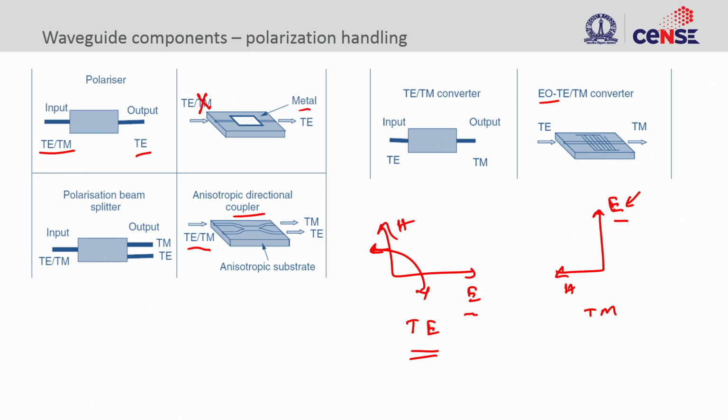So, that is another way of handling polarization conversion. You can also do it through passive means similar to what we saw here. So, you could have TE come in and then rotate the polarization, but not in a single waveguide. Perhaps you can have some structuring along this that will rotate the polarization, okay, which is something doable, or you can use directional couplers as well.